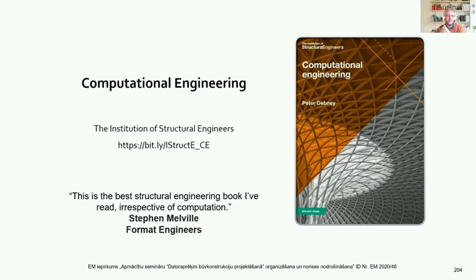That will give you a pretty good approximation to a taper. Obviously, you need to break it down quite a lot. In tests that I've done, one taper needs to be broken down into at least 4 or 5 individual pieces to give you a similar behavior. So just break it down, vary each section, and then analyze it to make sure it's good.